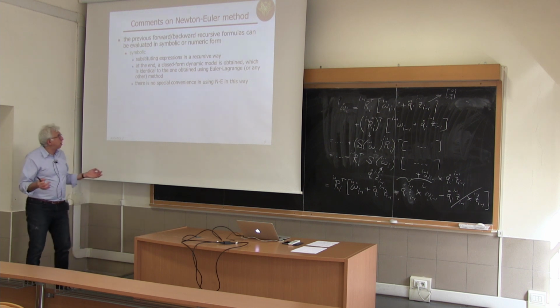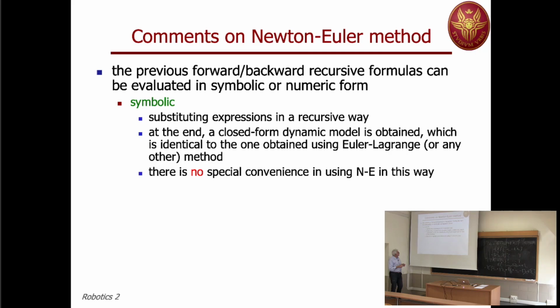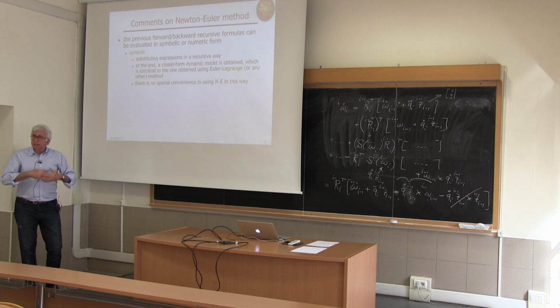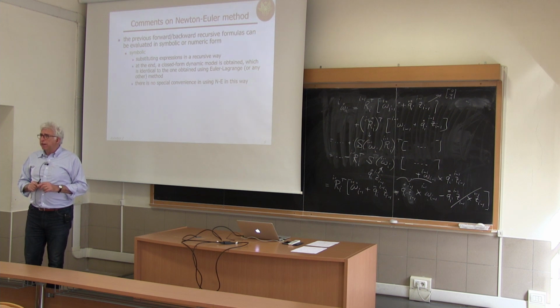This is a very important comment, so that it's not really written here in this slide, but it's something that people are starting to realize while doing identification. So the summary is that you need the full dynamic parameters if you want to use Newton-Euler's, not just the dynamic coefficient. So either the manufacturer or the CAD provide this to you, or you cannot use this system, in much the same way as you need those parameters when you're doing simulation with systems like VREP or Gazebo, which implicitly use the Newton-Euler recursion. So they need to define for each body those parameters, even if they are not going to use those parameters.